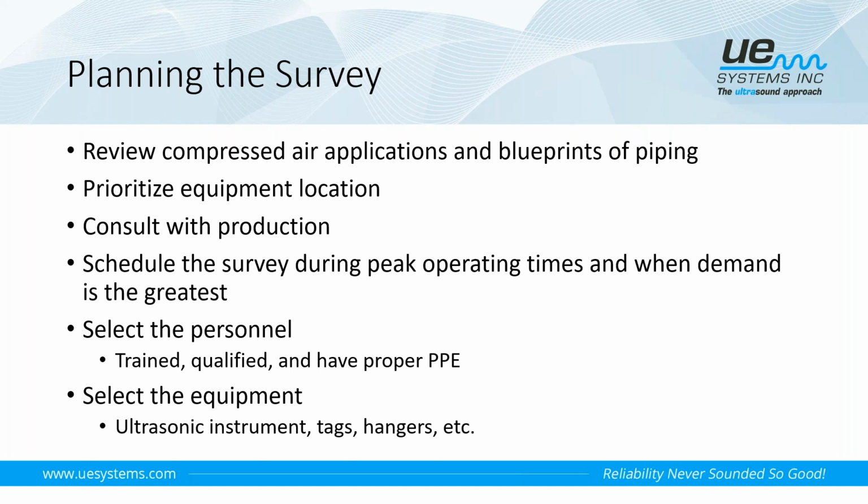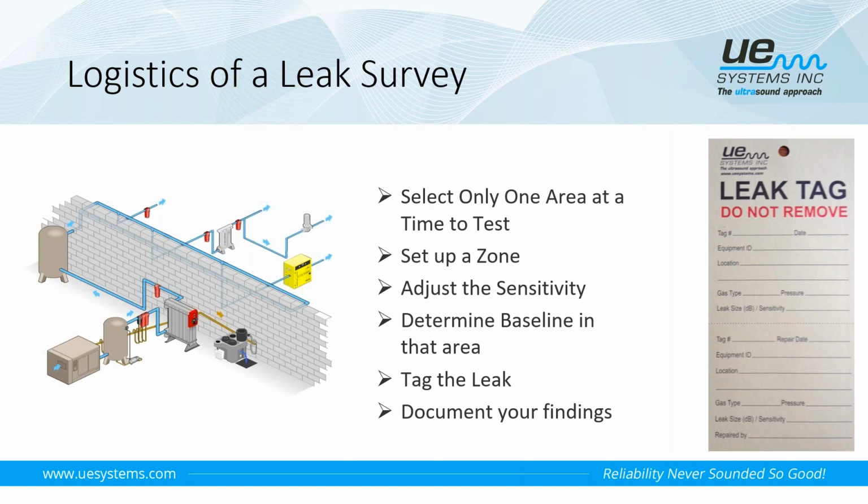We use those sometimes as shielding techniques. So we talked about how high frequency sound has a tendency to bounce and reflect off of surfaces. Well, you can use that clipboard or you can use that wipe rag as a way to help block out any competing noise that might be in the area. It just makes it easier to pinpoint exactly where that leak is coming from.